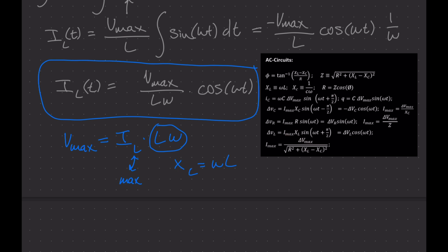Very cool. Now I think we've covered most of the equations, and like I said, when we derived these using those Kirchhoff loop rules, again, keep those in mind. You most likely won't have to derive anything like this from exams, but it's good to know where things come from and what things mean. But you saw when we derived these couple equations here and using Ohm's law, we actually came to notice that these things here were defined that way because these are kind of the resistances of the capacitor and inductor. So keep those in mind.